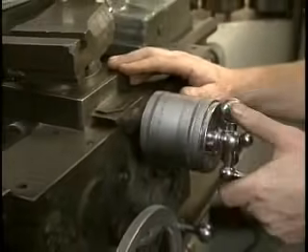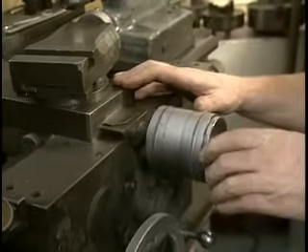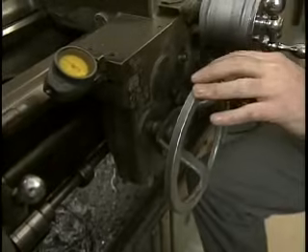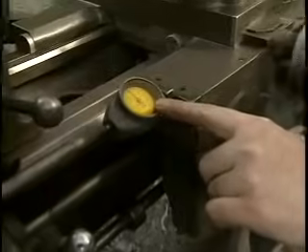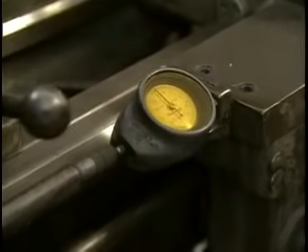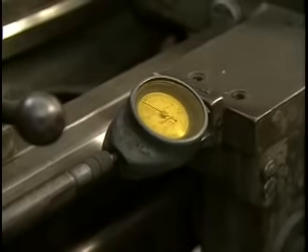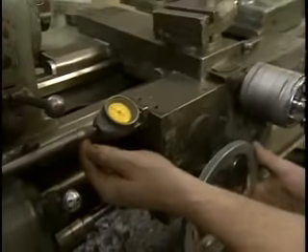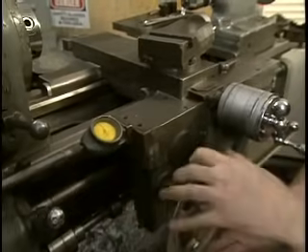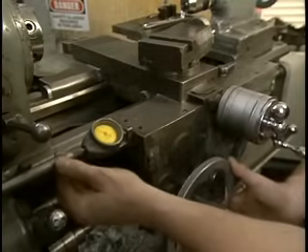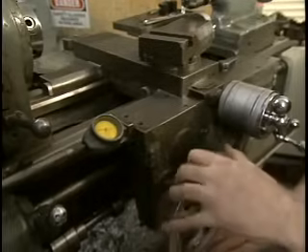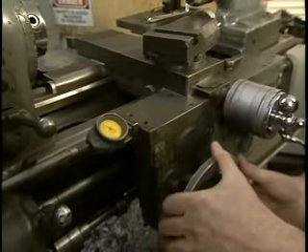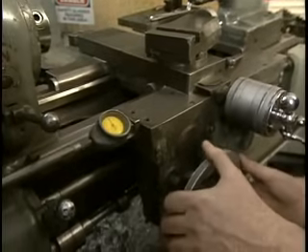The cross slide can be accurately positioned using this dial. But on most machines, the saddle does not have an equivalent dial. What you generally use with a saddle is a dial indicator like this with a stop. You bring the dial indicator in contact with the stop so you know where you are on that pass. You can then adjust the micrometer so that you can take a deeper pass. For example, we want to go another 10,000ths of an inch on the next pass. Set the stop there, come down, and when we're machining, carefully bring the saddle down until the indicator indicates 0.